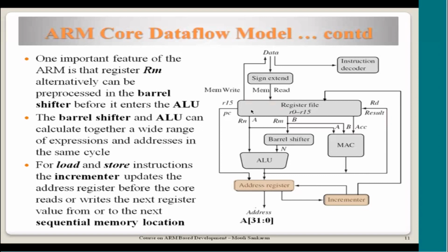So some 5 or 6 register contents need to be copied to 5 or 6 locations in the memory. Now the address is automatically incremented by 4 starting with the first access, and the remaining accesses are also completed in the sequential mode. So to perform the sequential access of memory, this particular incrementer and the address registers are used for the data access.